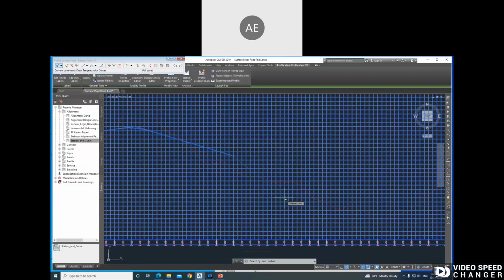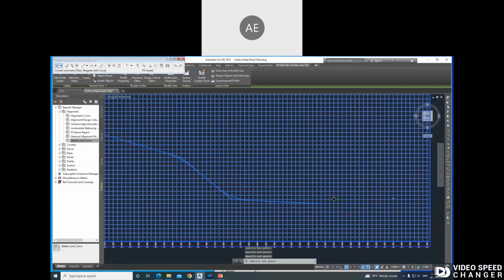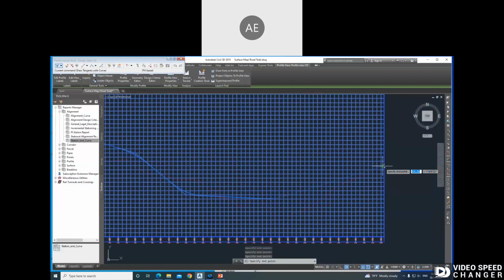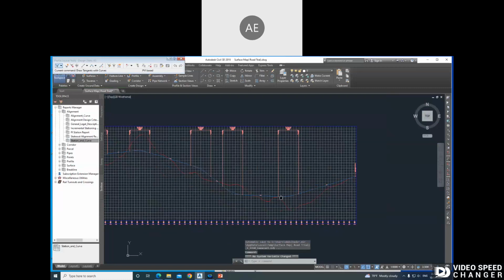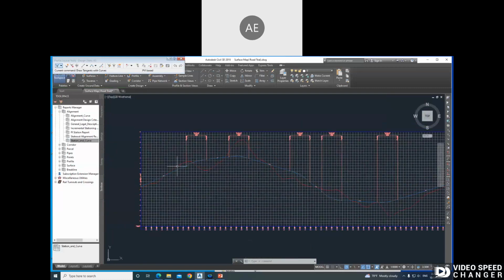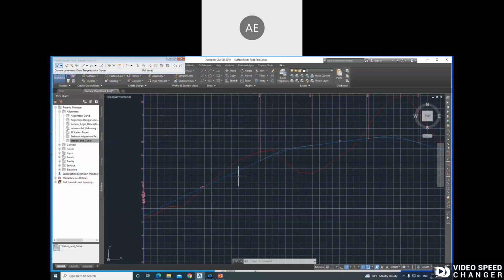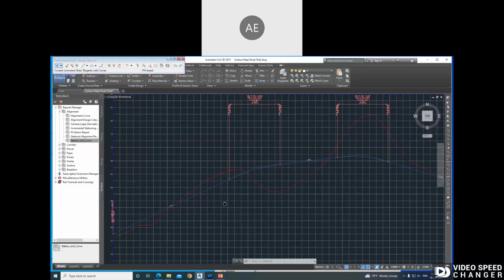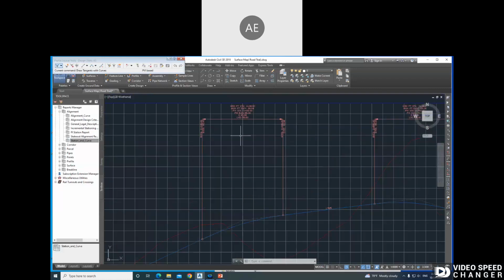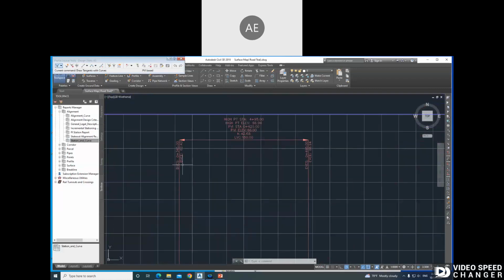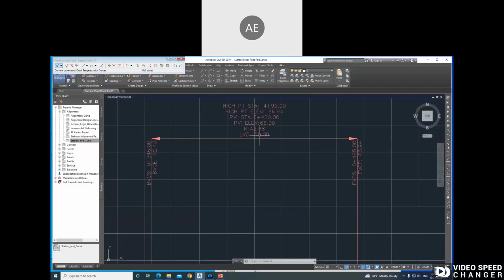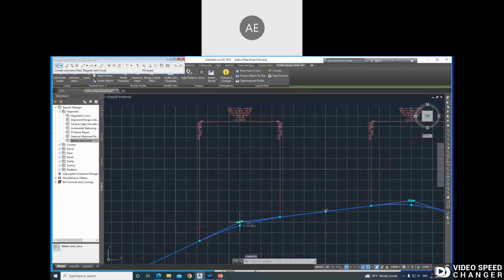Okay, so now we are just drawing the design. So enter the design level, the proposed new one. You see, look, the blue one is the design, the new elevation, the proposed elevation, where my cars will pass through without any issue, hopefully. You see, at each transition between points, of course, I have curves, as we learned in surveying or in transportation. The beginning of the curve, end of the curve, the length of the vertical curve, 150 meters. And all of these can be adjusted. You can adjust them depending on the space that you have.